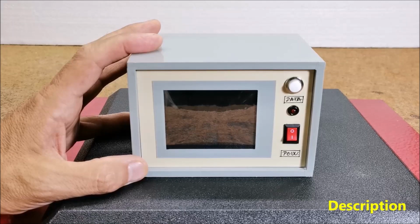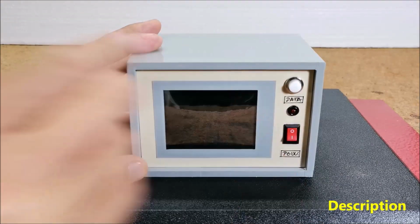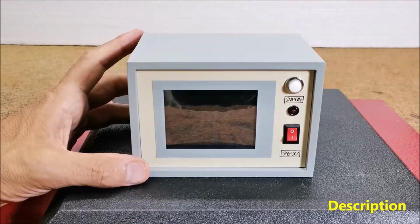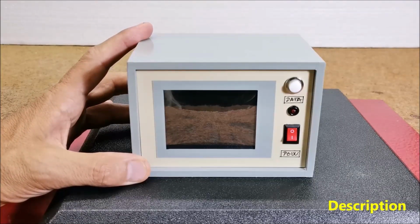According to the code, the sensor is active for 30 seconds while taking a reading, then shuts down completely for 4 minutes and 30 seconds. The active period of the sensor is indicated by this red LED. Instead of putting the sensor into a low power mode, I chose to simply switch off the sensor's main power through a small MOSFET transistor.